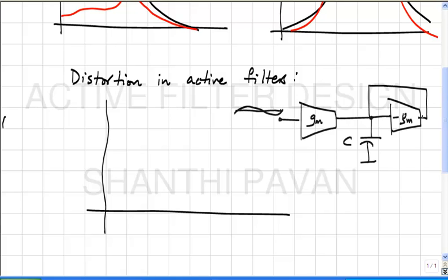Okay. Now what do you think happens to the output voltage? This is the output voltage. Very good. Okay. So when we say low frequency, what do we mean by low frequency? In other words, we basically mean that the reactive current through the capacitor is very small in relation to the current through the resistor, right? So if the current through the capacitor is extremely small, almost small enough to be neglected, then let's see what happens.